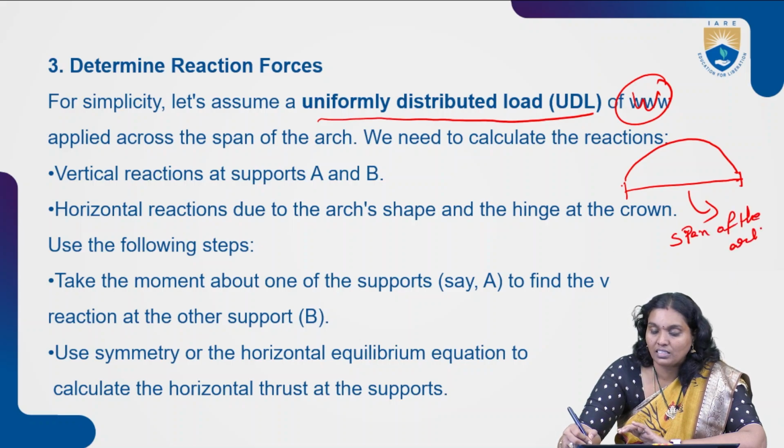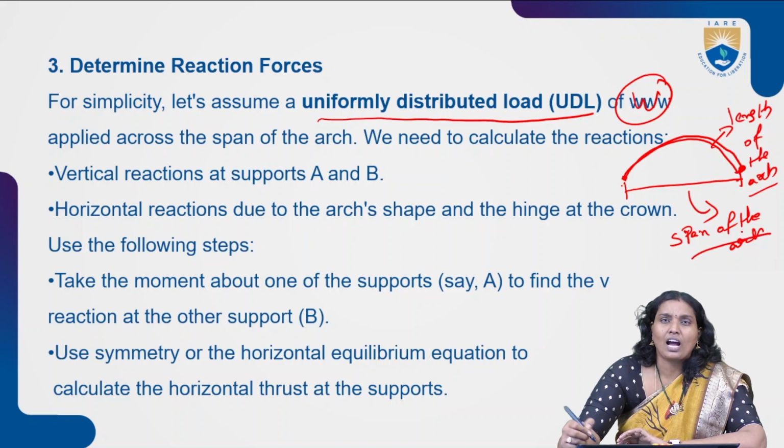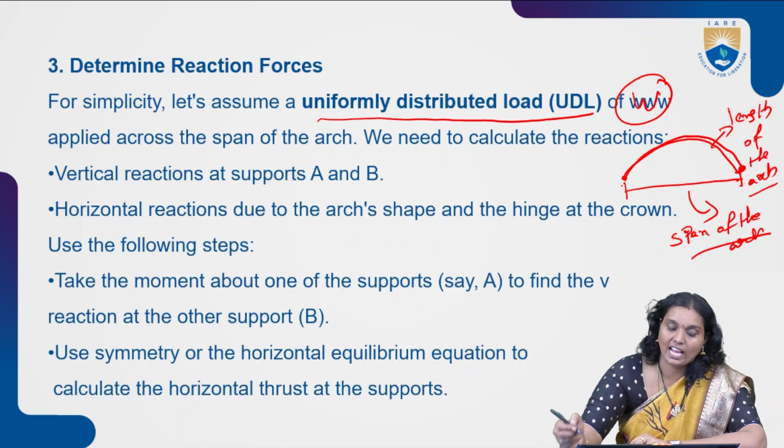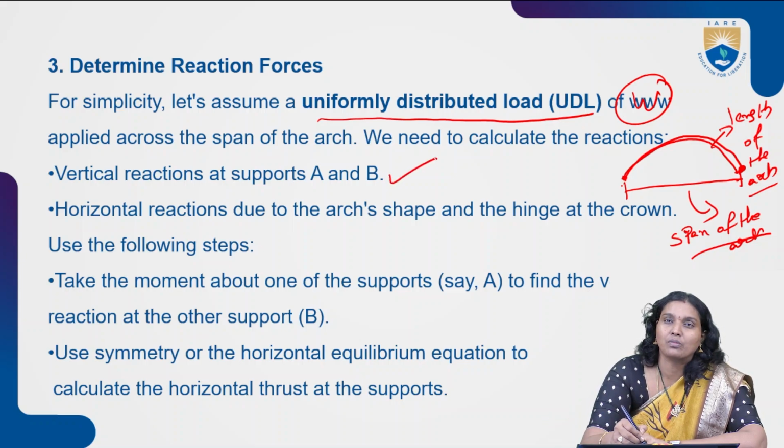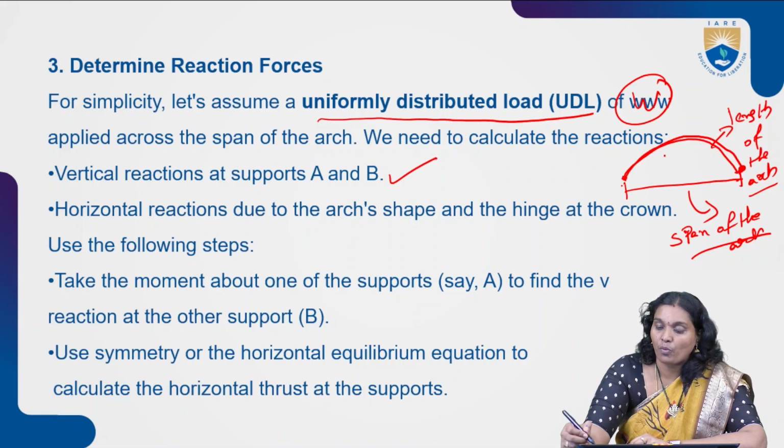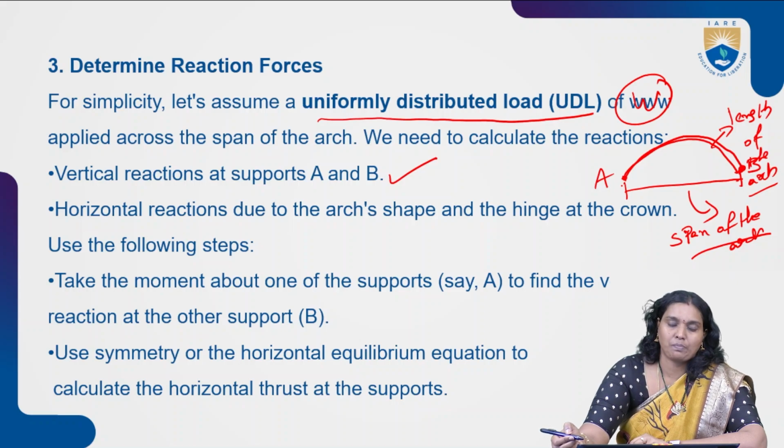Span of the arch, and the complete length from starting to ending along the arch is the length of the arch. The length of the arch and the span of the arch are two different parameters which we have to understand in arches. Whenever a load is applied across the span of the arch, we need to calculate the reactions. Those are the vertical reactions at the supports at the starting point and the ending point. We may consider A and B as the starting and end supports respectively.